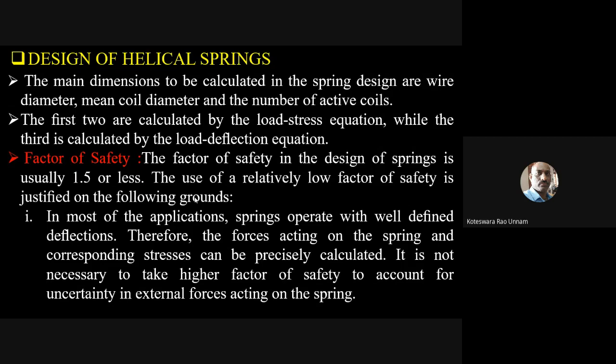In that you have a load P. If I know exactly the P value which is going to act on the spring, then there is no need of considering the factor of safety. If I have some uncertainty in determining the magnitude of P precisely, then we need to go for a higher factor of safety. In most spring applications, the load which comes onto the spring is determined more precisely. That's why a low factor of safety can be used in case of spring applications.